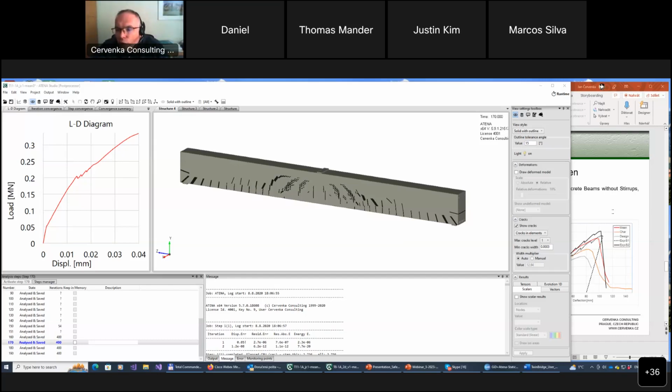But I also want to bring to your attention that once you finish your analysis, you can define a monitor in the postprocessor. You can define a monitor request, which can then extract other monitors which you originally didn't think of, which is often the case: you perform the analysis and then you say, oh, I would like to extract some data from some quantity at some location, and I don't have a monitor.